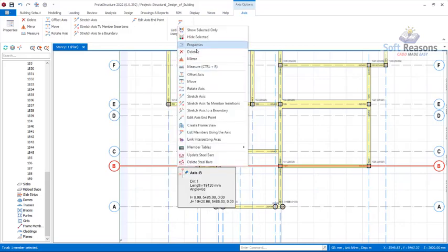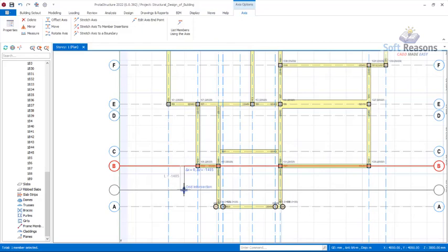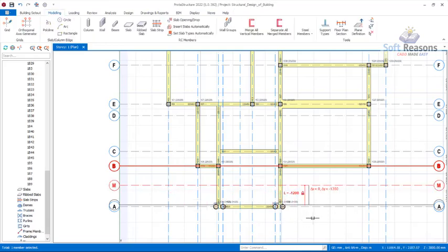So you right click right there and click on the offset option. Move your hand downward, hold the shift key and then F2 to have a prompt to key in the distance. So I propose minus 1200 since we are going downward. It's going to be 1200 millimeters, and enter.